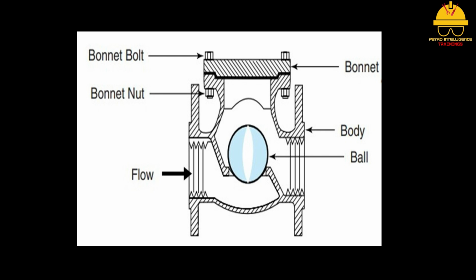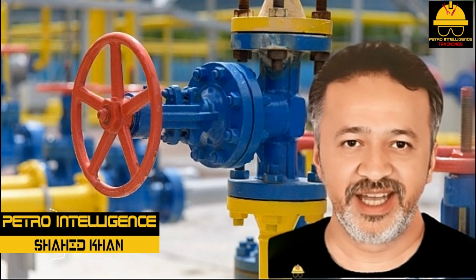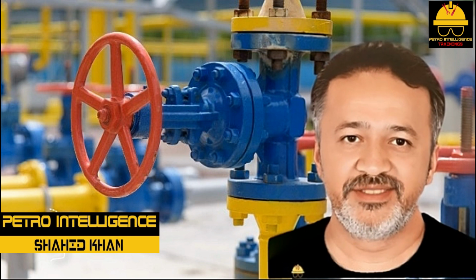Like the swing check, it is designed to close when flow reverses. Ball checks are ideal for systems in which flow rates fluctuate or the fluid contains some solids. The ball check is as durable as a lift check and more durable than a swing check.